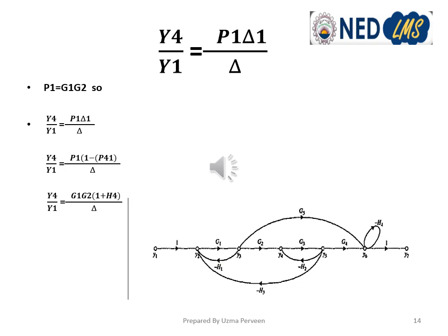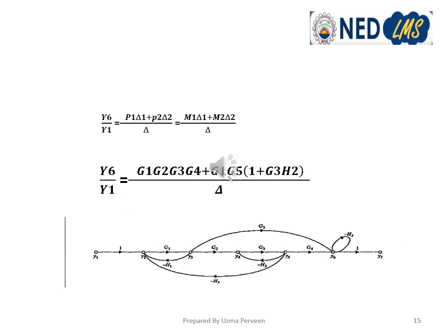So after calculating Y7 upon Y1, Y2 upon Y1 and Y4 upon Y1, the method is quite clear to all of you, I hope. So to calculate Y6 upon Y1, this time we have to see the forward paths from Y1 to Y6, and we can see easily that there are two forward paths, so we'll count it. The remaining method is same.